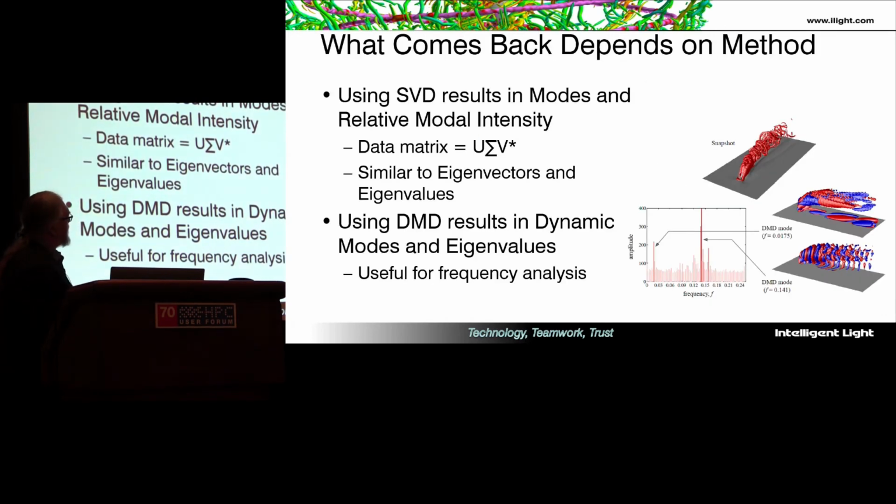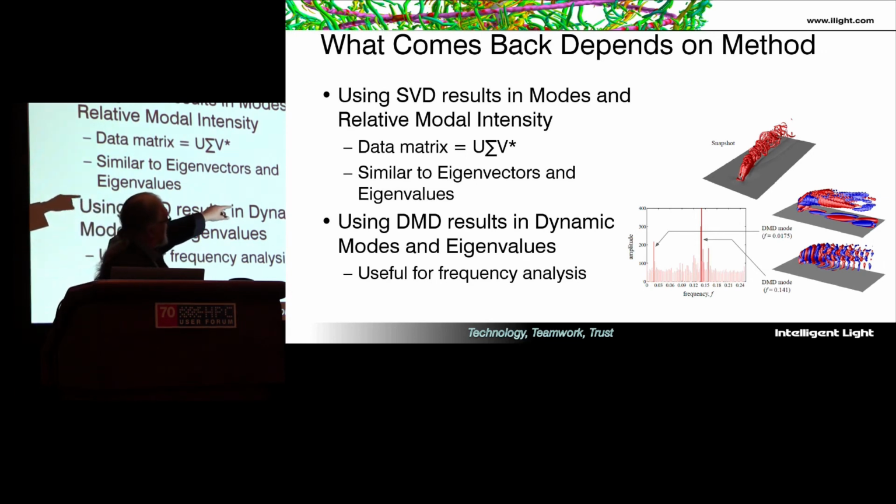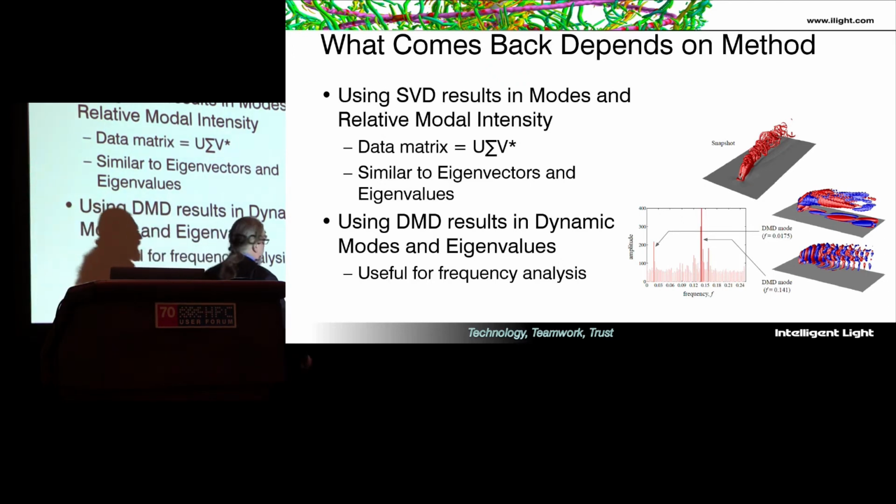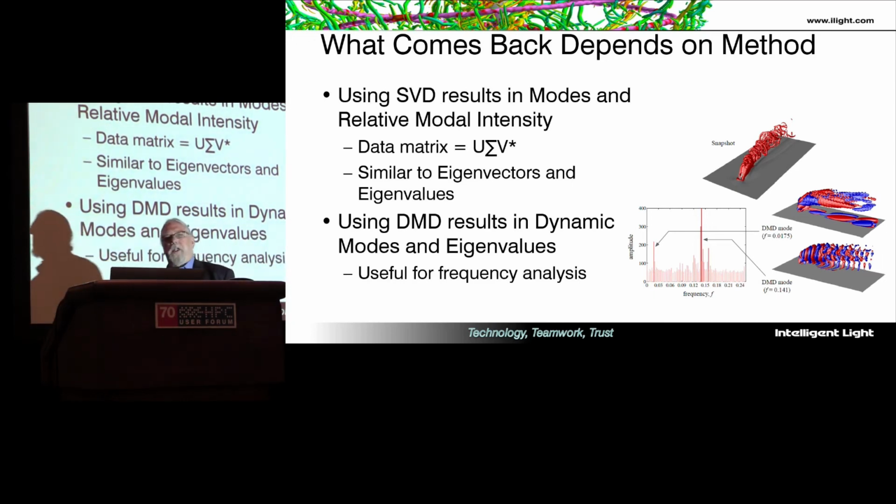Things can get more complex. This is dynamic mode decomposition. So this is a cross-flow jet, the red thing. And you take that data, you put it into a matrix, you do dynamic mode decomposition, and you essentially get eigenvalues of frequency, which you can then reproject into the CFD space. And so this is the physical energy corresponding to this frequency. And so you can start to understand complex 3D machines in other spaces. Very important stuff.